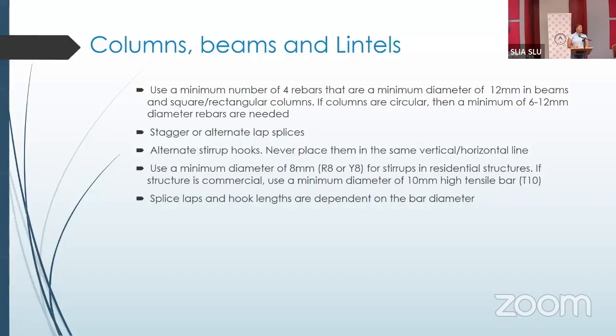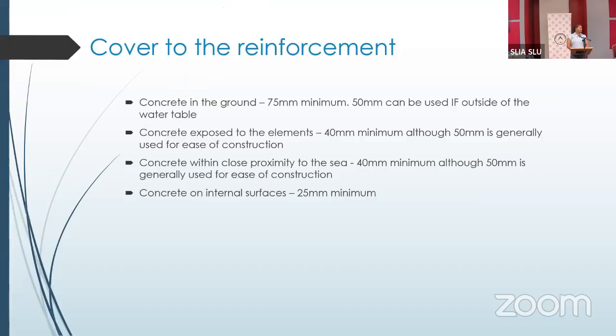For the splices and laps, you'll have heard me say so probably a million times within the last 10 minutes. Your cover to reinforcement, if it is in the ground, generally your minimum cover to reinforcement is 75 millimeters or 3 inches. Now there are times when we can get away with 50 millimeters or 2 inches, but then that means that your concrete must be